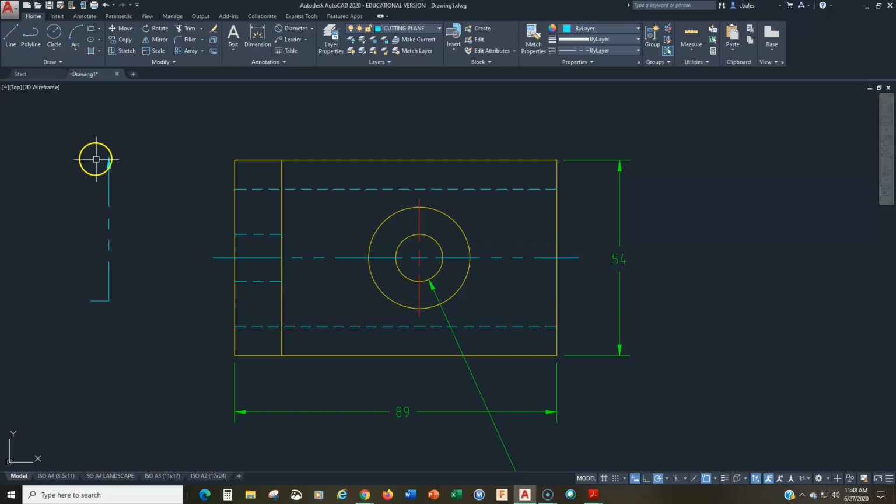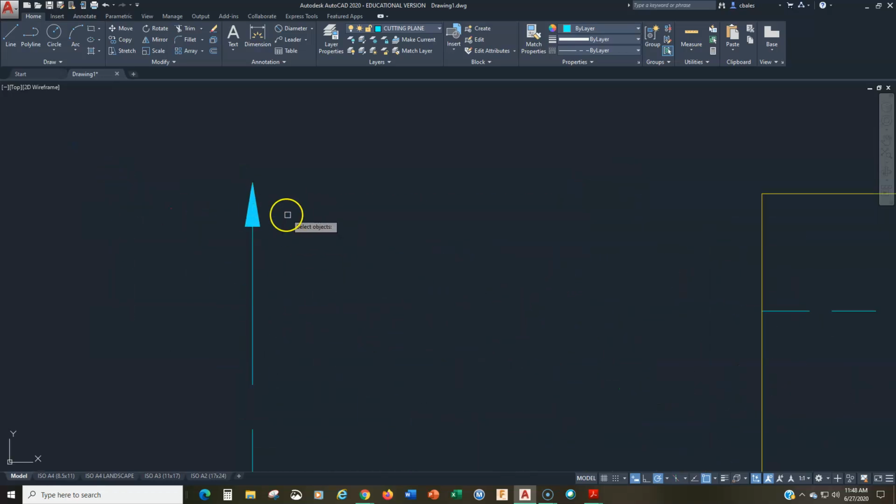And now, what are we going to do with this? Well, let's fix this first. The arrow is too small by 1/2. So I'm going to go to the scale command, and I'm going to window just the arrow. Let me zoom in here so you can see.